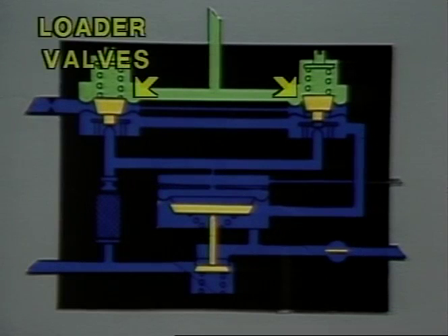The loader valves do not close at the same time because their adjusted spring tensions and diaphragm sizes are different. A precise calibration of the loader springs is critical to achieving a smooth start.